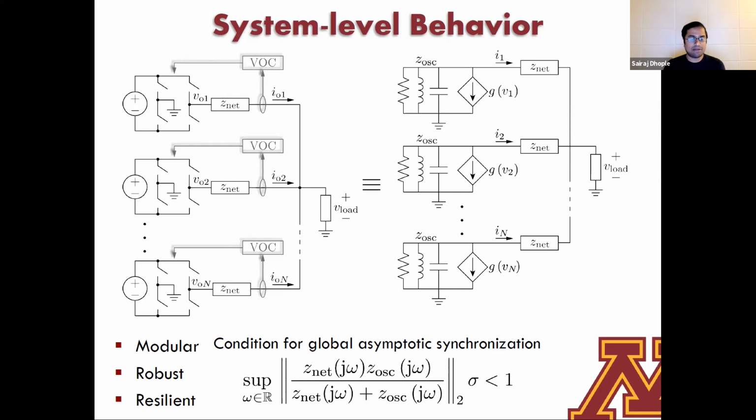And then I'll also mention that it's resilient, because in order to get this fairly strong condition, I'm able to realize this with no communication beyond what I'm having implicitly or inherently via the electrical interconnection of these inverters. So the only thing I'm leveraging here is the electrical interconnection in order to get this condition for synchronization.